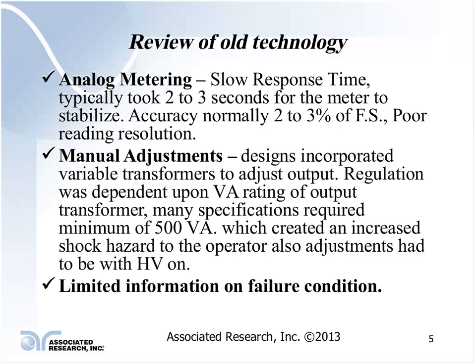Again, the older instruments typically had manual adjustments. So, you were looking at a variable transformer that was used to adjust the output voltage. The regulation of the equipment itself was really dependent upon the VA rating of the tester itself. Many of the standards specify yet today that you have to use a 500 VA rated Hipot tester to perform some of these tests.